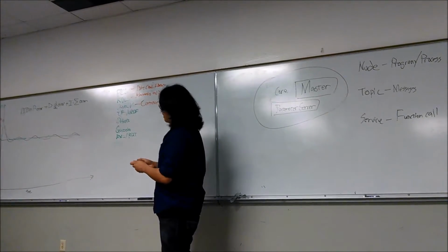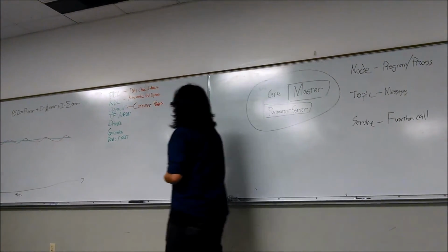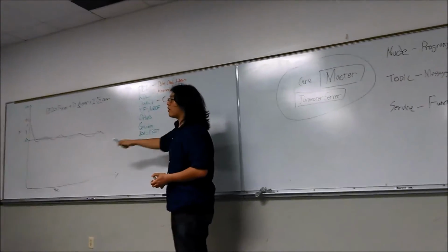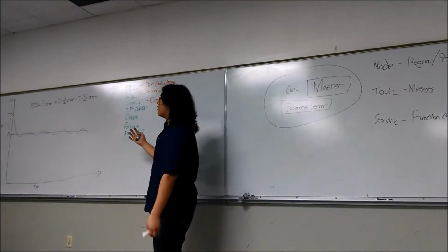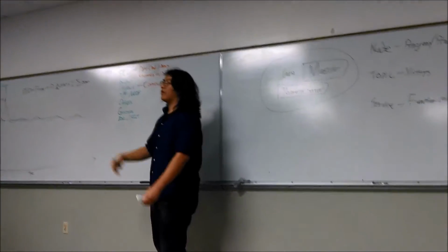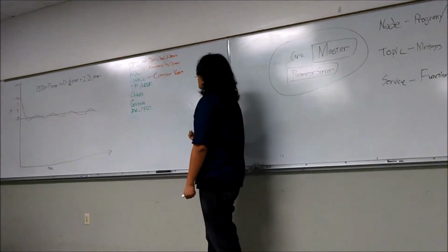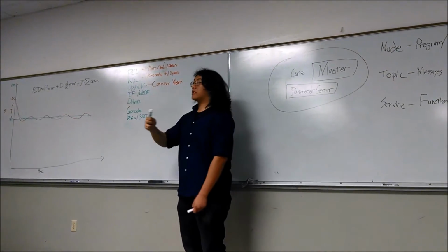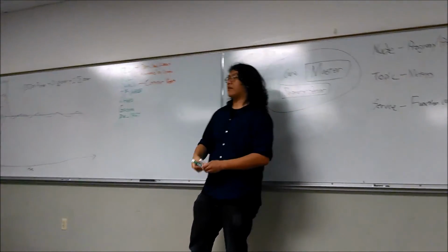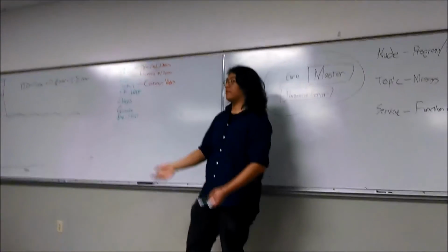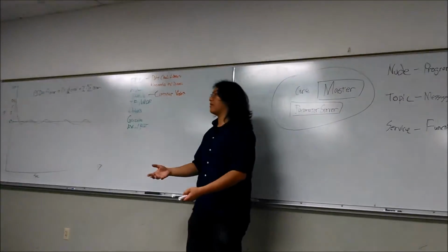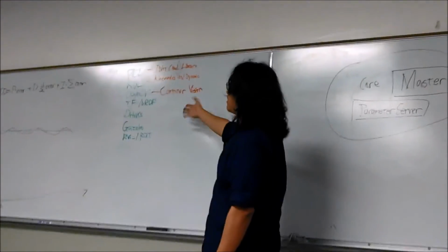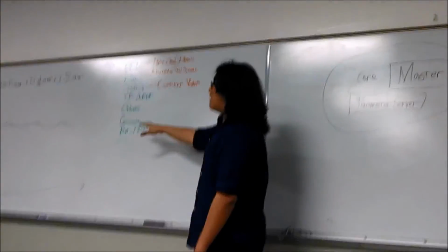TF and URDF. TF talks about transforms. Earlier I talked a lot about frames. TF is the package in ROS for your robot to maintain an account of all of the frames that it's aware of. URDF is an associated package which takes a model of your robot. So if I have a CAD, a computer-aided design of some kind of model of my robot already made, I can translate that to the URDF format, which ROS uses.